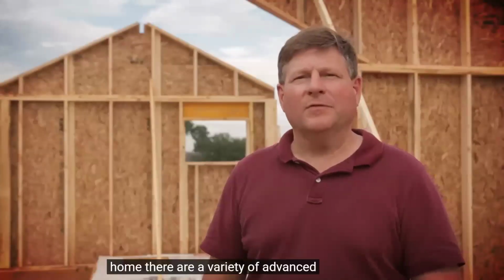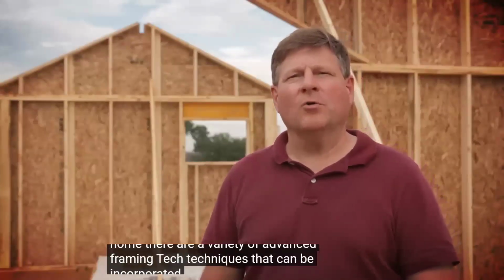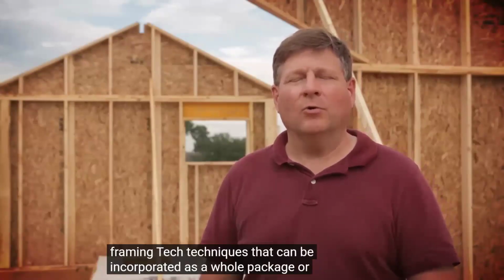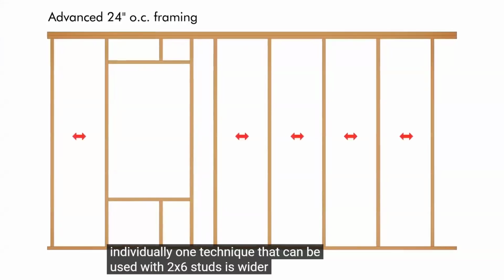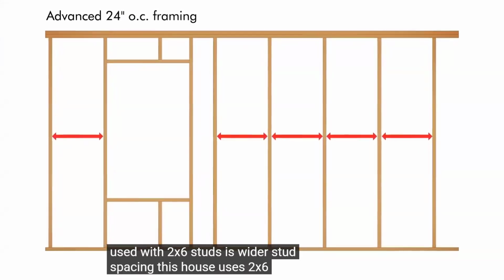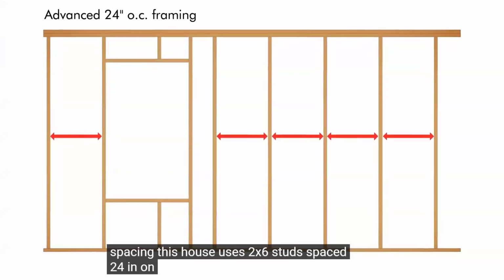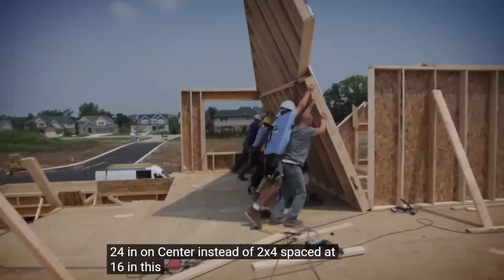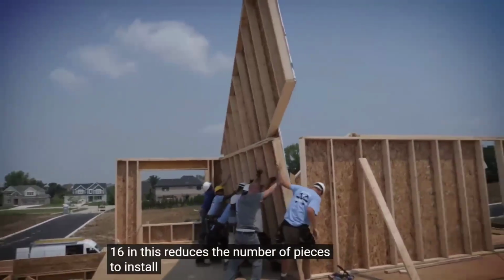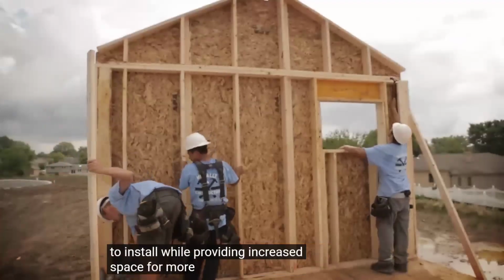There are a variety of advanced framing techniques that can be incorporated as a whole package or individually. One technique that can be used with 2x6 studs is wider stud spacing. This house uses 2x6 studs spaced 24-inch on center instead of 2x4 spaced at 16 inches. This reduces the number of pieces to install while providing increased space for more insulation.